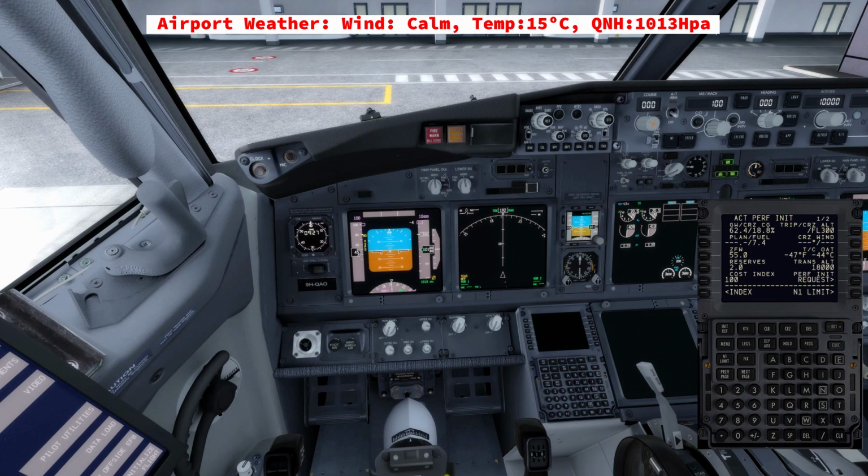And that is even why, when we take off from a narrow runway, let's say 30 meters wide, we always try to reduce the thrust as much as we can in order to have less yaw moment. So basically, the nose of the aircraft going left or right depending on the engine failure. Because we have a narrow runway.